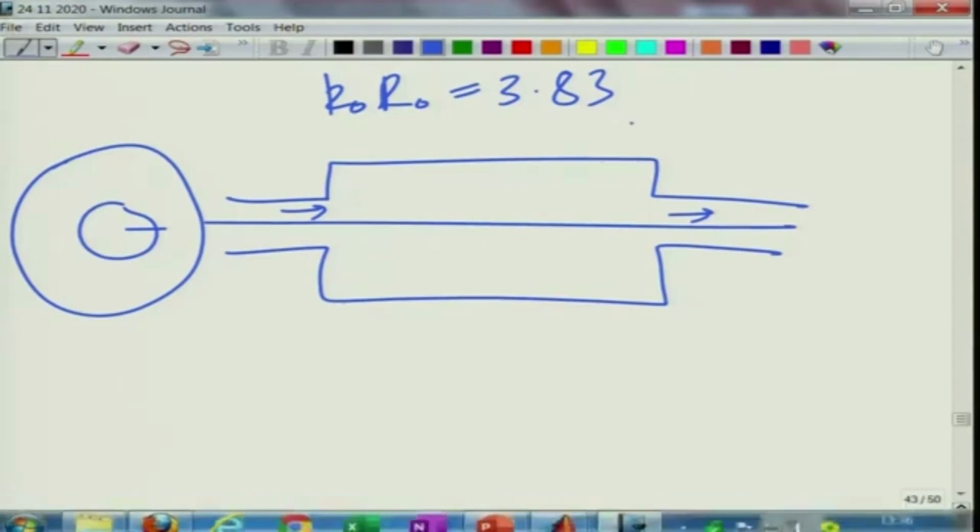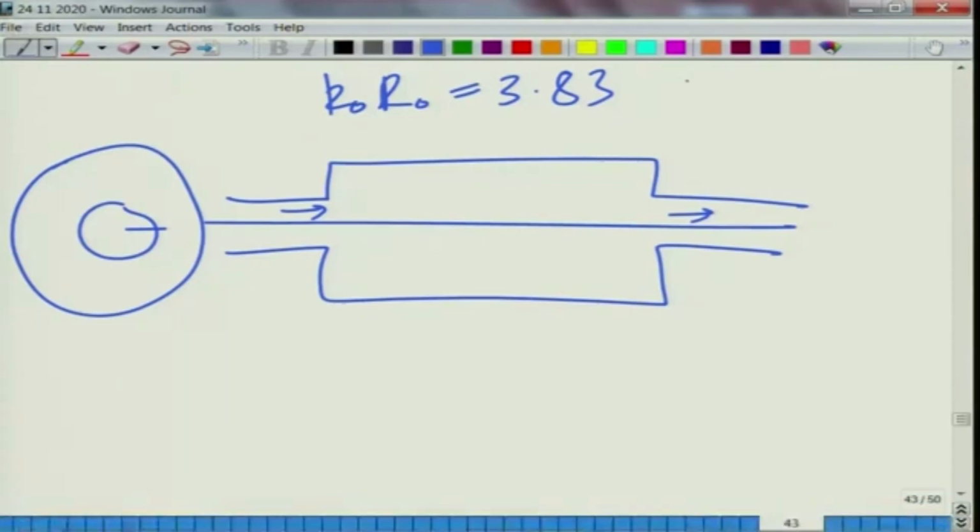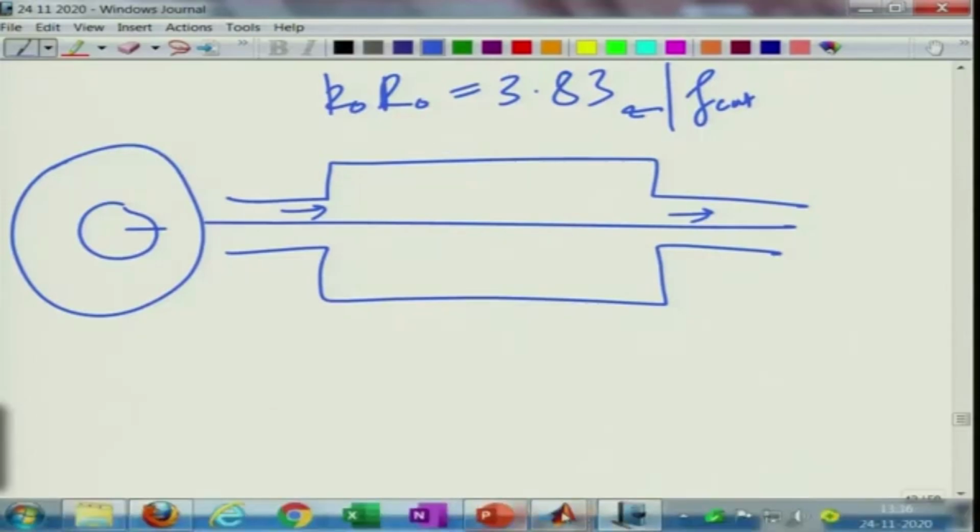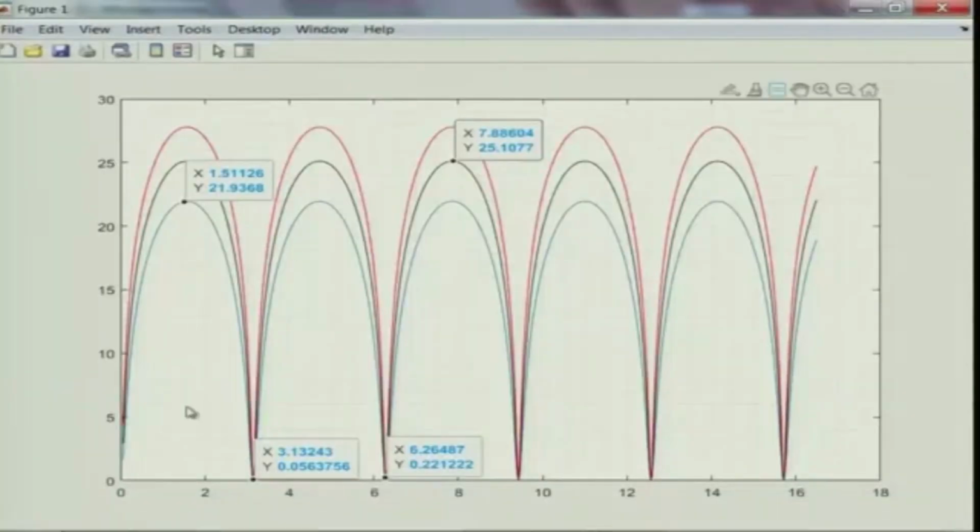The point I am trying to make is that we can obviously calculate the cut-on frequency based on this expression, at which the radial modes will start propagating. So, the nice beautiful dome-trough pattern, this is the dome, this is the trough, and so on, will break down just before the 0 1 radial mode starts propagating. So, at what frequency does it happen? It happens at a certain frequency which is given by the radius of the chamber.